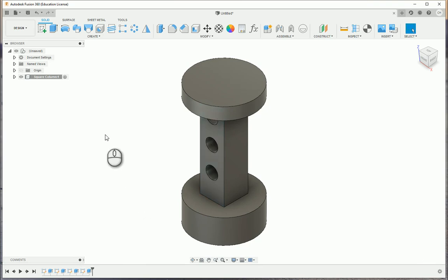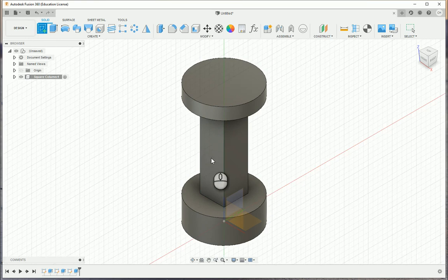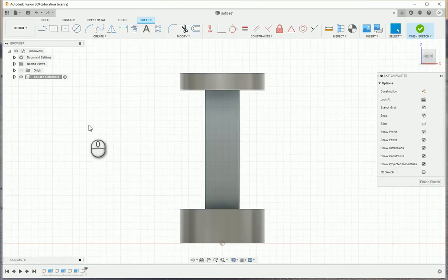One thing we're going to do to start off with those scoops is edit some of this. We're not going to start all the way over or hit undo, but we're going to right click and say delete to get rid of the extrusion. And there's the sketch. I'm going to right click and delete the sketch as well. So we're going to keep everything else, but we're going to start a new sketch on that square column.